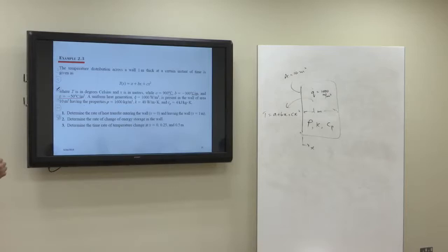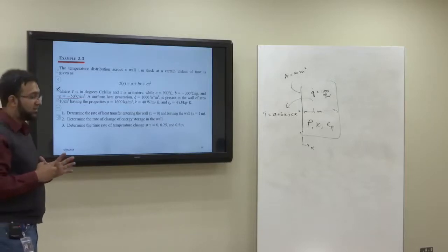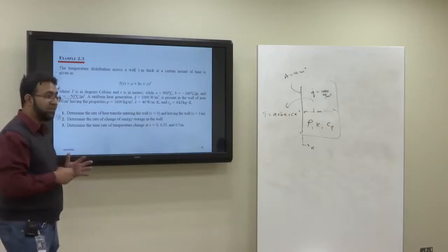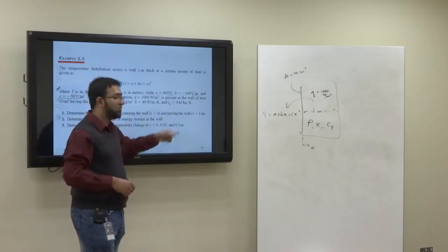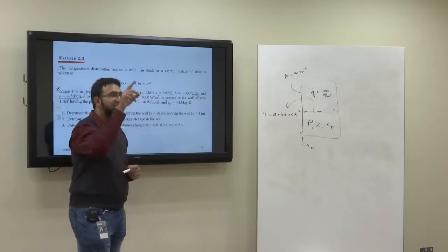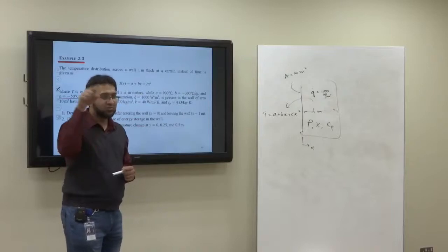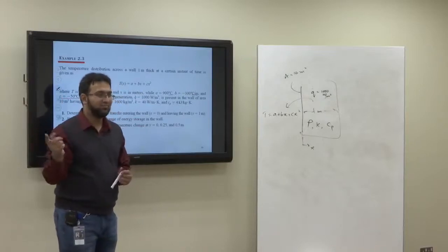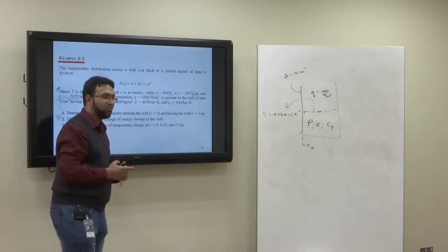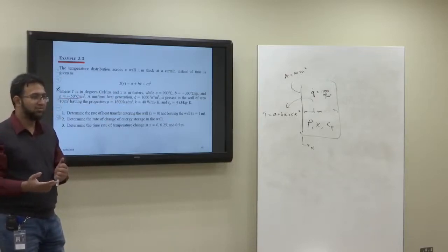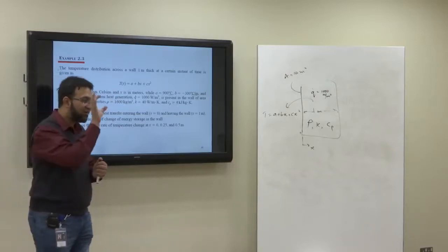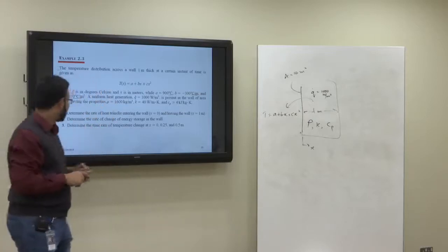Now, as I tell you, always be focused on the units. Sometimes the units are played in a very tricky way. For example, if you see here, the value of Cp is 4 kilojoule. When you are solving everything, kilo should come as 1000. If you directly use the value with 4, then something will go wrong. So always try to focus on the units.